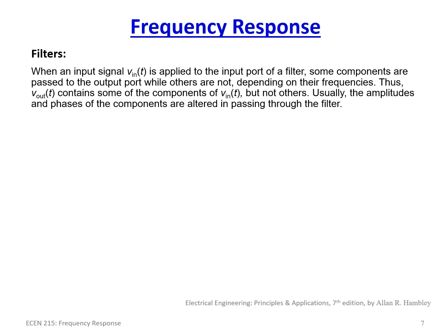If we put a capacitor in there, we would get the exact opposite effect. We would start out at 0 volts and eventually be equal to the amplitude of Vin, which for argument's sake was 1 volt. So we have an input signal Vin and an output signal Vout. We could call these an input port and an output port, and we have some sort of device in the middle, whether that was an inductor, capacitor, an RLC network, some component or components changing the output versus the input based upon frequency.